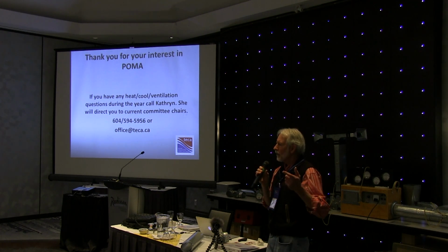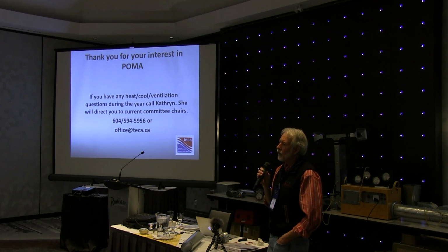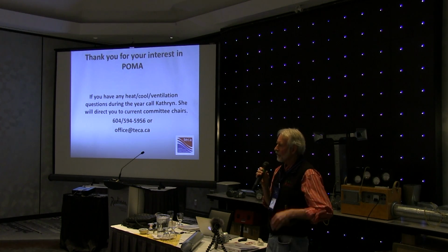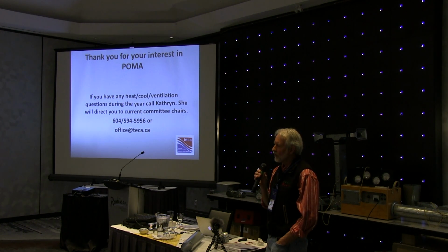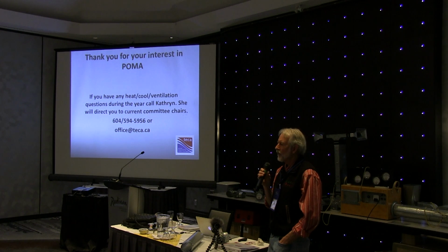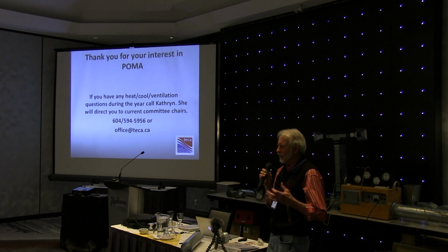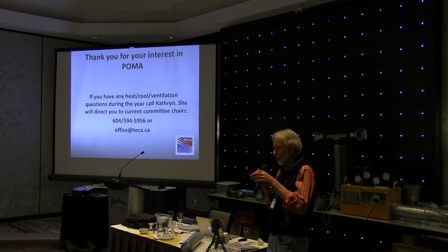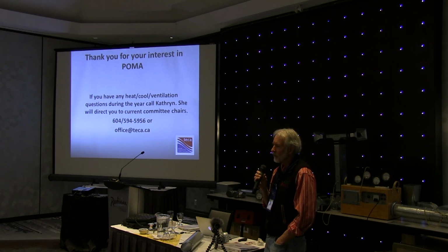For example, I was out in Squamish doing this course about 2 weeks ago, and I heard of a 4-ton piece of equipment going with two 8-inch round ducts for return. What we have to do is have tables in front of us, supply tables, return tables, and at least look for minimum duct sizing based on those tables, based on the CFM of that appliance. Because the manufacturers would support it. These manufacturers aren't stupid. They protect themselves with requiring a temperature rise and a certain external static pressure. We're exceeding those on many, many installations.